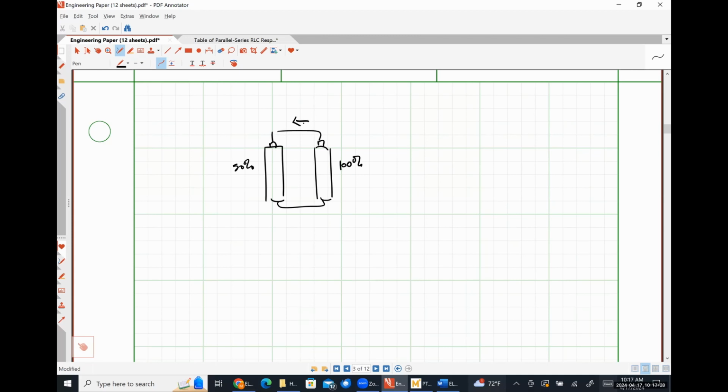Possibly. The issue with supercapacitors and all of that is just thinking about things in the context of a simple RC circuit and how long it would take you to fully charge one of those. The larger the capacitance is, the longer it takes to charge and the longer it takes to discharge. So in the context of a voltage regulator, that's a very good thing. If you have a simple electronics-based voltage regulator in parallel with a supercapacitor, it's going to make the output of that voltage regulator look like whatever voltage is stored in the supercapacitor.